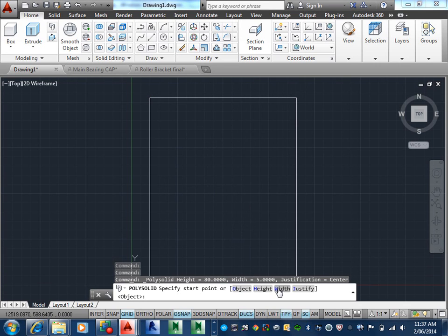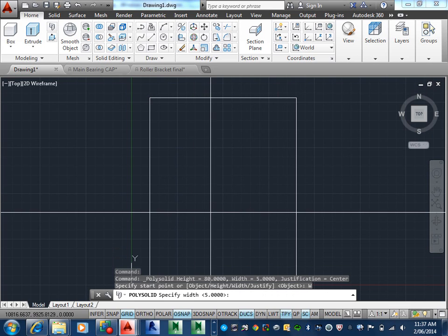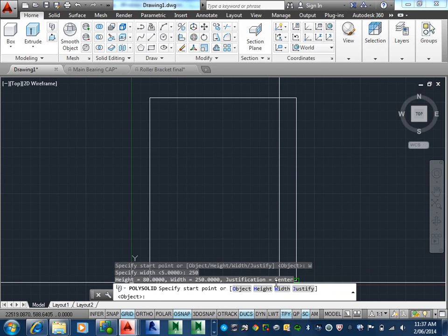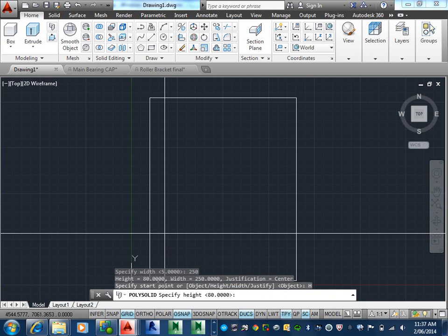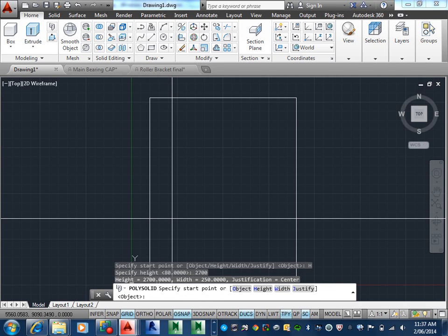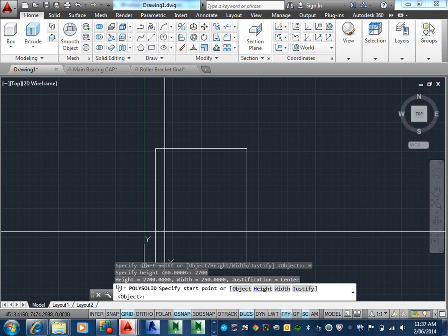They're not quite right to start with. So a typical house in Australia, brick veneer, will have a width of 250 millimeters. Enter that. Typical ceiling height of a typical house is 2400, 2700 perhaps. Nowadays they're increasing them to 2700, which is good. That was the 80s size I was quoting before. Okay, so I'll start somewhere, we can always move it.